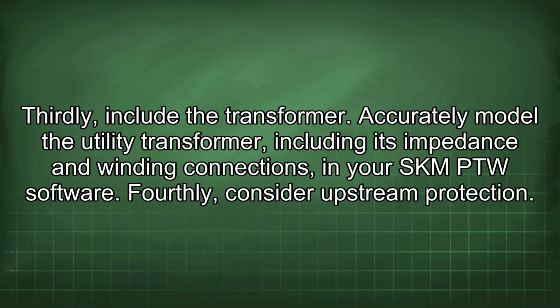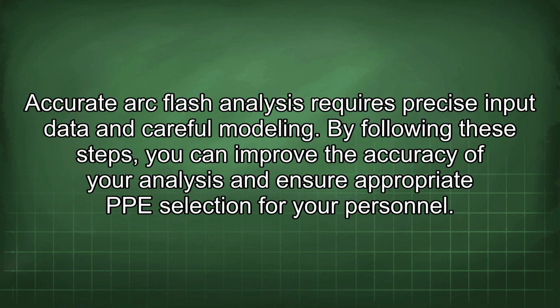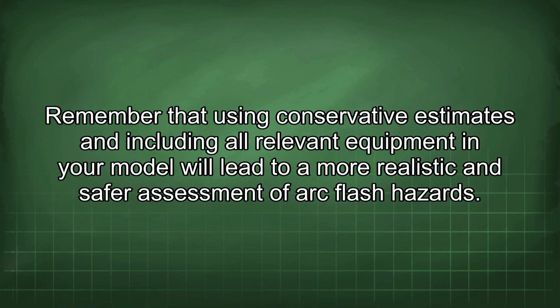Fourthly, consider upstream protection. Include upstream protection devices in your SKM PTW model to accurately simulate their impact on fault current. Fifthly, consult with experts. If you encounter difficulties or have uncertainties, consult with an experienced electrical engineer specializing in arc flash analysis. Accurate arc flash analysis requires precise input data and careful modeling. By following these steps, you can improve the accuracy of your analysis and ensure appropriate PPE selection for your personnel. Remember that using conservative estimates and including all relevant equipment in your model will lead to a more realistic and safer assessment of arc flash hazards.